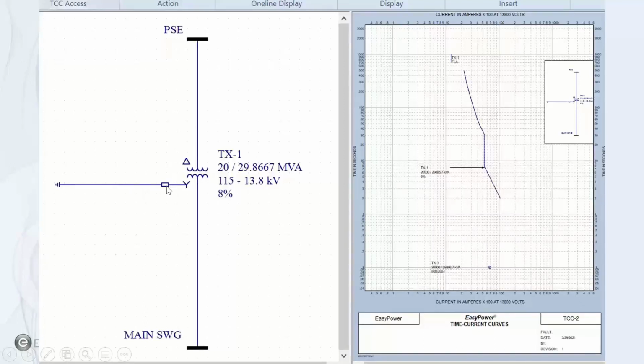Consequently, there's no concern about the single line to ground offset, and we would look at a specific current level that we would set a relay to trip at, and this will be orders of magnitude different based upon having the resistance in series. So we'll get into more of that next session when we talk about ground coordination.